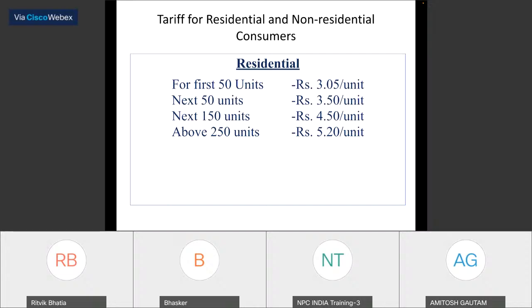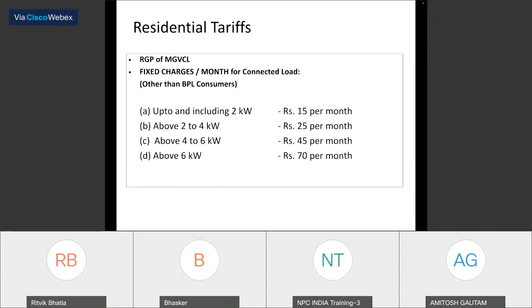And they could go from the last slab to another, third slab, and because of a difference of about 70 paisa per unit in a slab, they were able to get a deduction of 600 or 700 rupees per month. So it was very necessary to find out how I can go to the previous slab and find that my bill is reduced. This is the way we can find the reduction in the kVA, in the kW demand, and also the rupees which we can save.